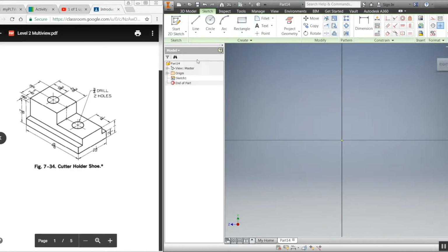So I'm going to go ahead, create the sketch, work my way around. First distance I'm going to do is 2.5 across the bottom. Hit enter, and then I can start making some of my distances up on this side. 0.5, and then the distance in is 3/8. So I know that's 0.375, or I could just do 3 divided by 8. Enter. I have that, and then the rest of my height is going to be 1 7/8 minus 1/2.